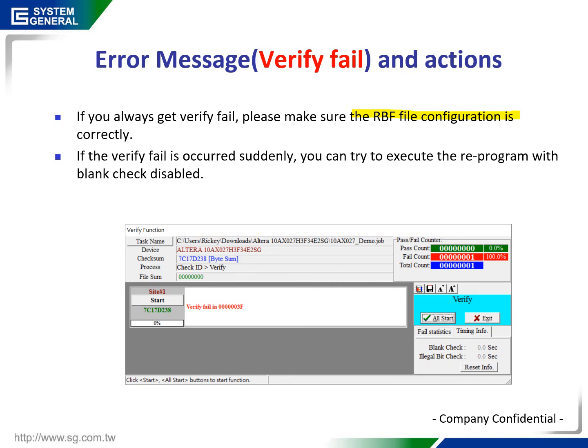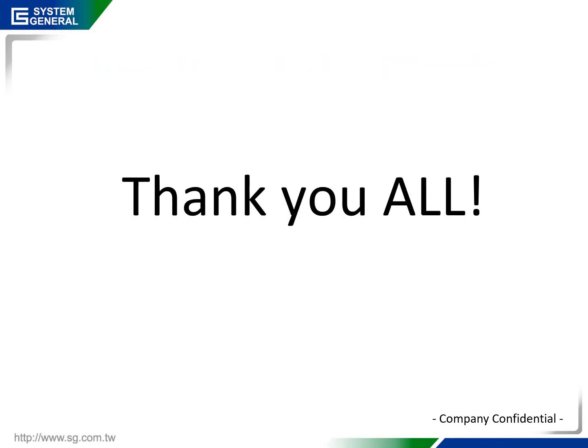On the other hand, if the verify fail occurs suddenly, you can try to execute the reprogram function with blank check disabled. The purpose is to make sure whether the verify-fail device has been programmed with the right design security key previously. When you disable the blank check function, you should be able to reprogram the device. Okay, so that is all of my SOP to introduce how to program the Arria design security key.